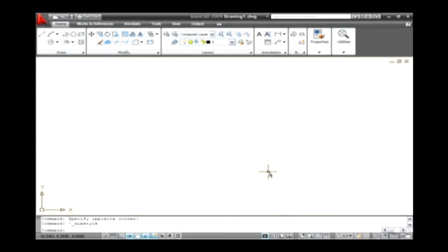Now, start the creation of a dimension. The current dimension style is followed for the dimensions. Whenever you want to change the style, you should open Dimension Style and select the style which is needed to modify or change, and select the Modify button to make changes in it. Finally, click on the Set Current button, and select the Close button to update the changes.